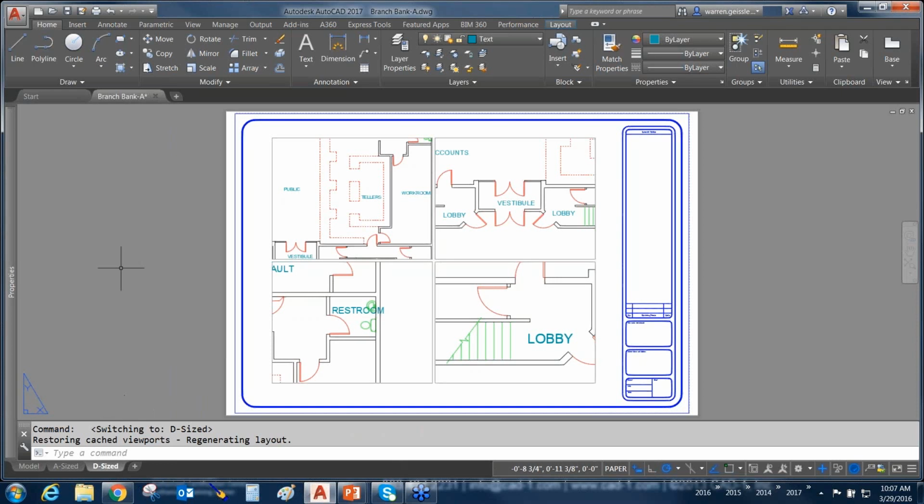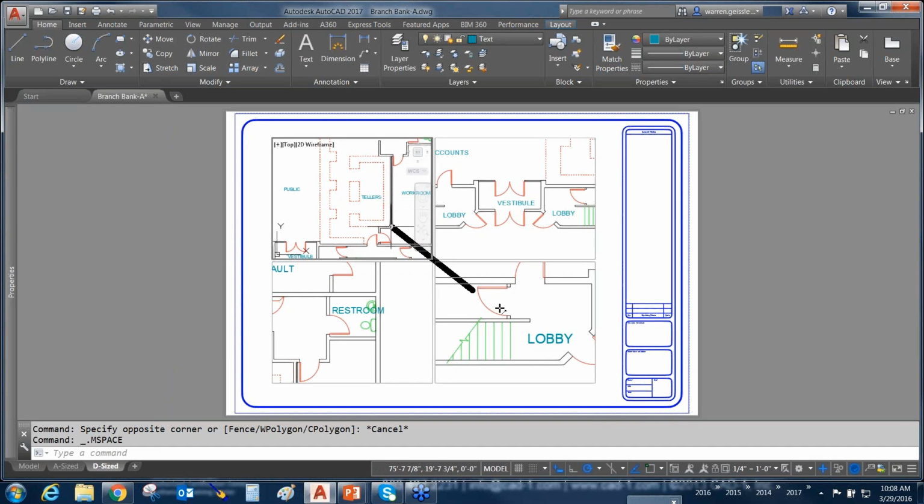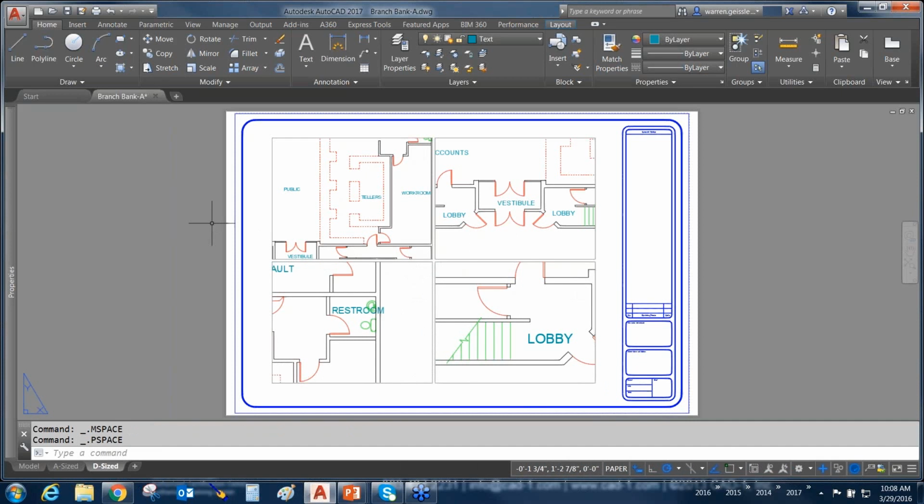Well, the problem arises when we flip on over to our layout tabs in our paper space and we set up multiple viewports for printing our drawing. And the multiple viewports, now everybody has been using different scales for the multiple viewports, different plot scales. So when I set up a viewport inside of my paper space layout, then, down at the bottom of my screen, I can set up a viewport scale. So you'll notice this viewport up at the top left is 1/4 inch equals a foot. That's how I want it scaled. The one that I'm going to switch to at the top right, 3/8 inch. Below that, 3/4 of an inch. And to the left of that, 1/2 inch equals a foot. So we've got all different scales that I want to print my drawing out at.